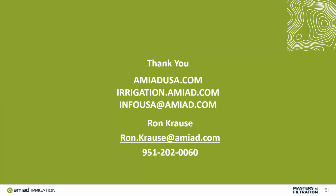Great. So I had a little two cents to chime in as you were talking about the max allowed pressure on the filter and the screen, keeping that in mind, and then combining that with maintenance. I used to work out in the field and repaired all kinds of stuff. What I saw from an improper disc size or screen size, compared to the water quality, crushed those screens pretty darn quick. So I'm just stressing the importance of always making sure those screens are cleaned, because not only does it affect the pressure and the system itself, but it completely destroys the inner workings of those filters in general. Just wanted to reiterate that. Very good point. Very good point.